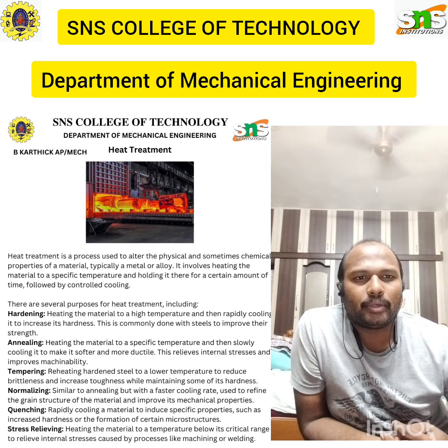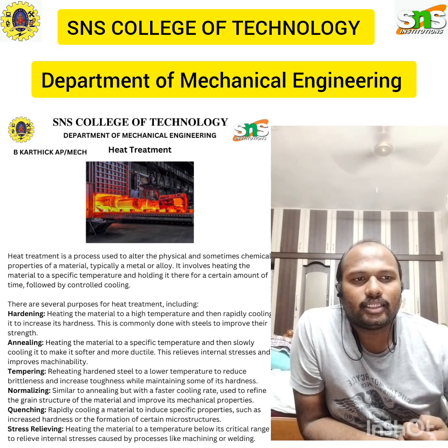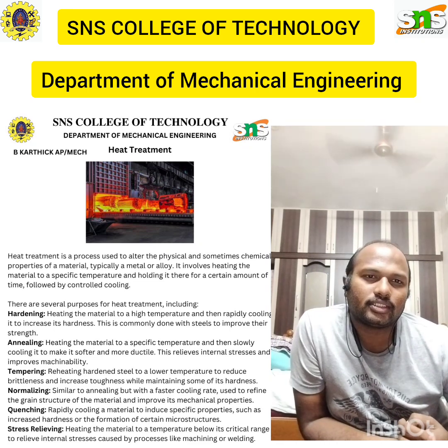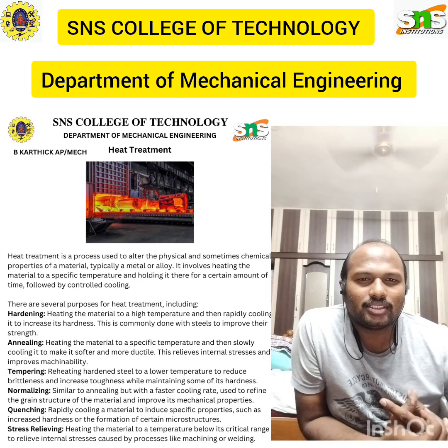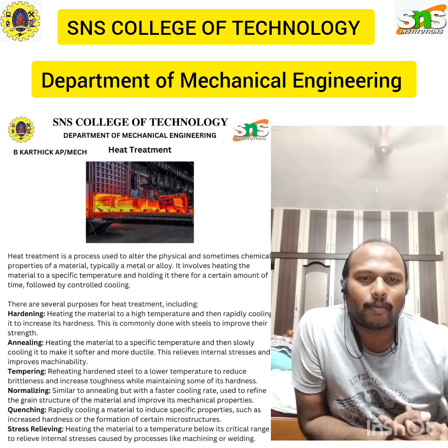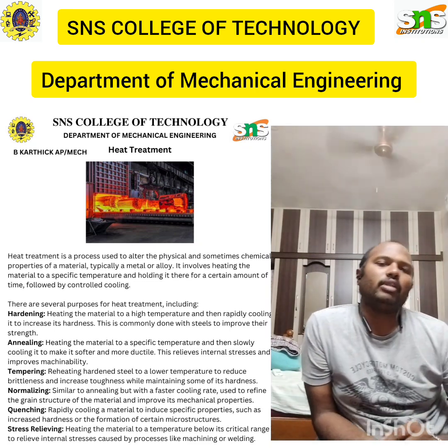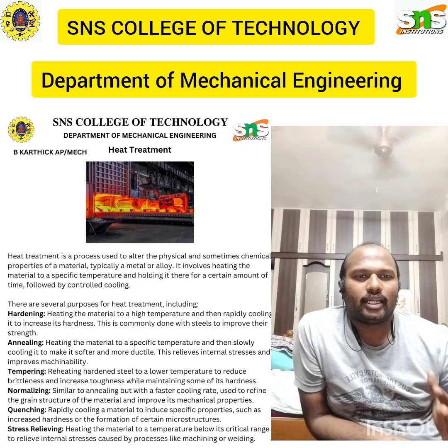And coming to tempering: reheating a previously hardened material to a lower temperature and then cooling it, which reduces the brittleness and internal stress while maintaining the hardness and strength. The tempering process is just like a twin of the hardening process. We never do the hardening process alone. Most probably we do hardening, and after the hardening, we will do tempering.